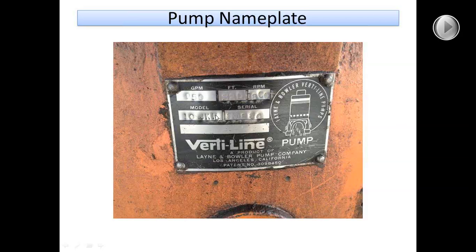We looked at pump curve programs a little bit yesterday. I can go right into the manufacturer's pump curve program and enter these numbers in. I can just enter probably the design operating conditions, 950 gallons a minute at 320 feet of head, and tell it to go 1,800 RPM pump. And it'll probably come up with this model number as one of my options. And I can just select that pump, and I have the pump curve for the pump.